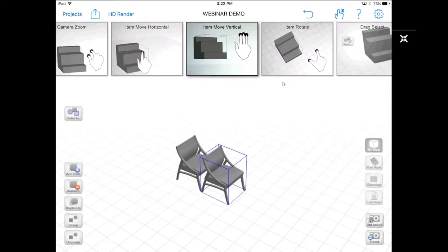Now, the manufacturers have set certain insertion points for some of the furniture items, like hutches, which recognize the standard heights the credenzas or work surfaces are supposed to be at. So those hutches will come in at the appropriate height so that they can be placed directly on top of whatever surface you have. That's intuitive, and that's created by the manufacturer for the actual data set that they provide us.